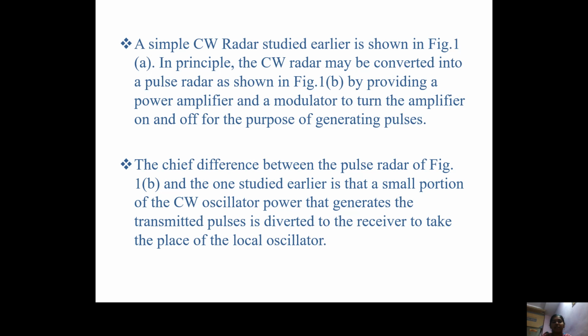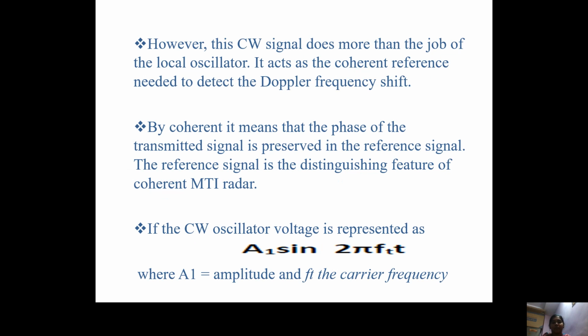And as I have discussed earlier, in the case of MTI or pulse Doppler radar, the continuous wave oscillator acts as a coherent reference needed to detect the Doppler frequency shift. As I said earlier, the continuous wave signal does more than the job of the local oscillator. It acts as the coherent reference needed to detect the Doppler frequency shift.